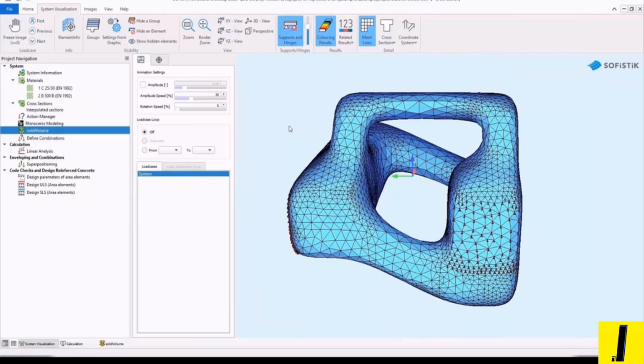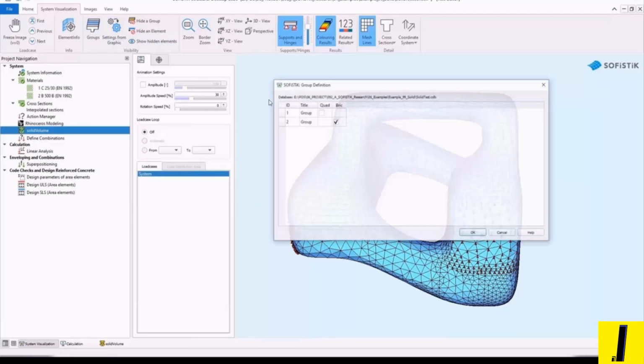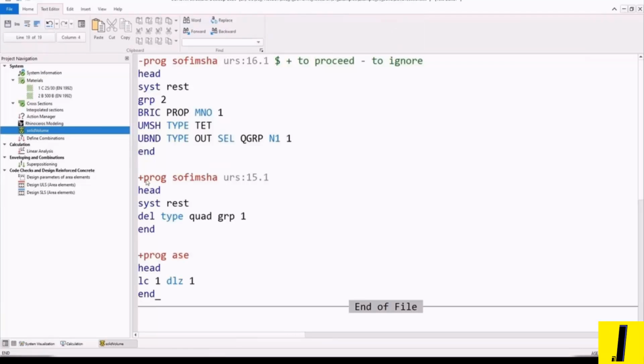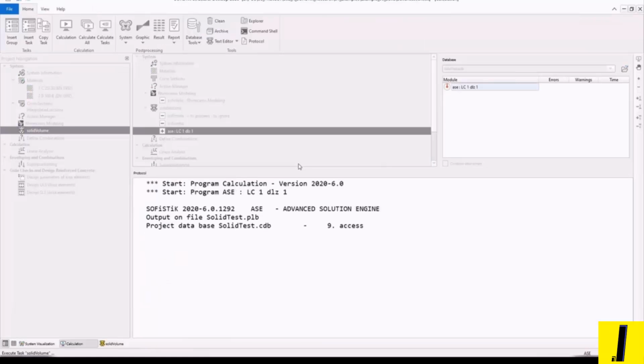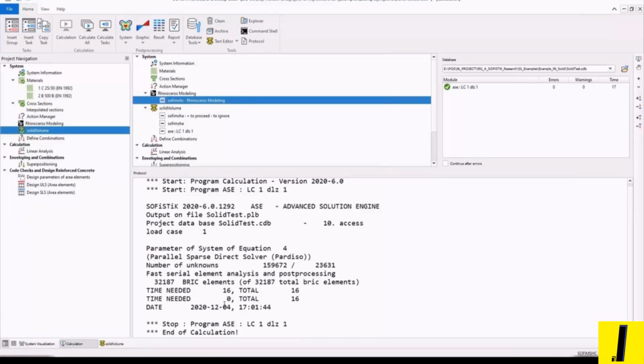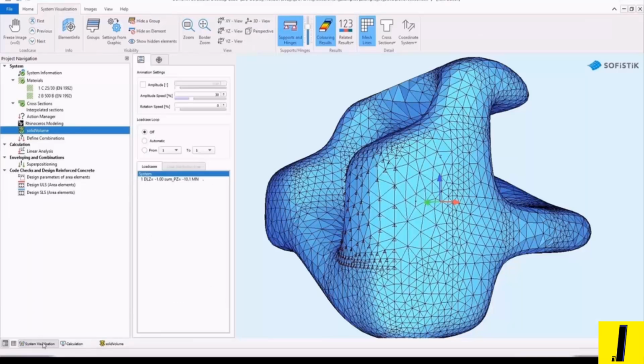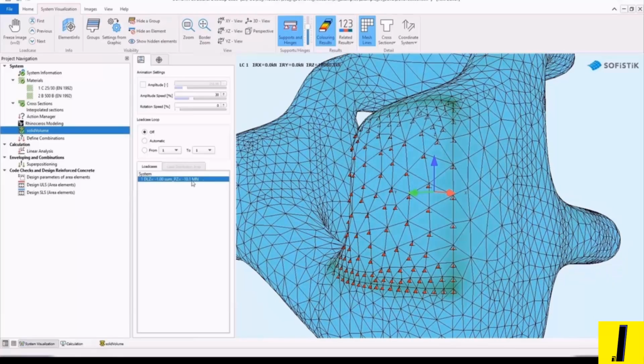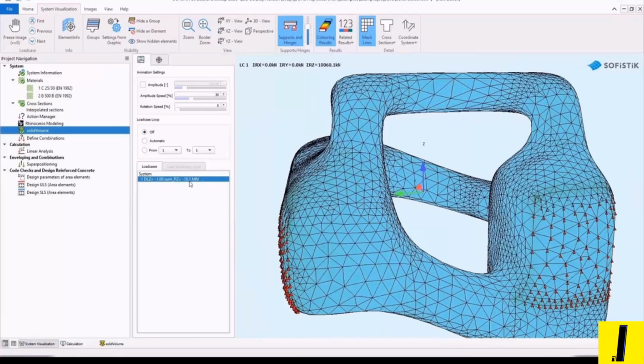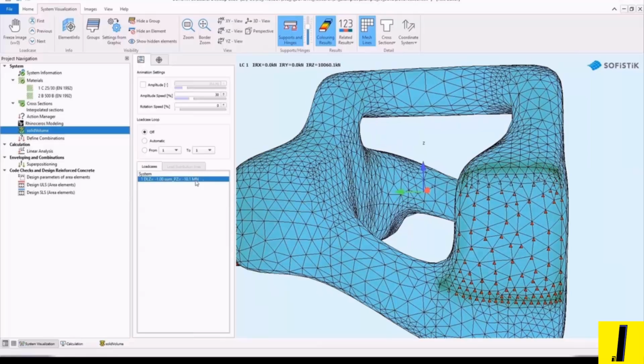This SubD geometry is very interesting. We can easily manipulate organic geometry shapes in Rhino, and then we can convert this volume, or solid geometry, from Rhino to work in SOFiSTiK as a volume geometry, apply a concrete structure, and see how it works.